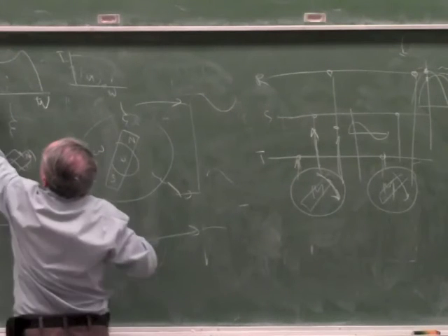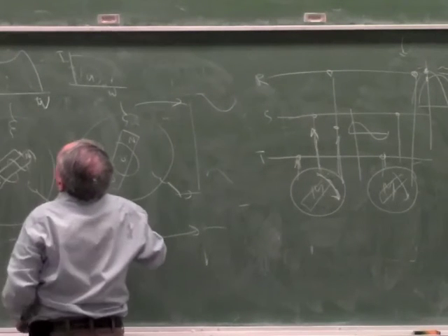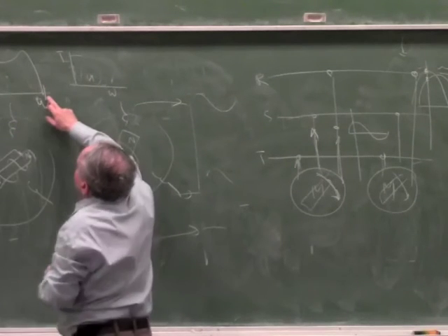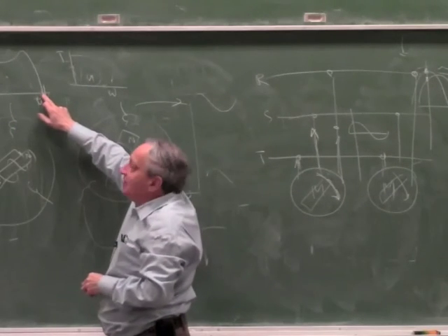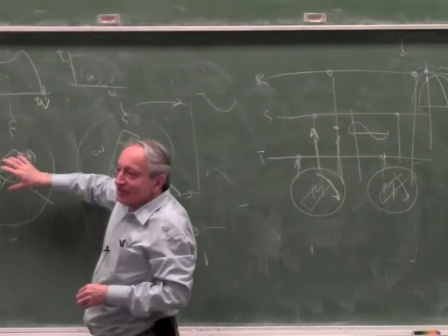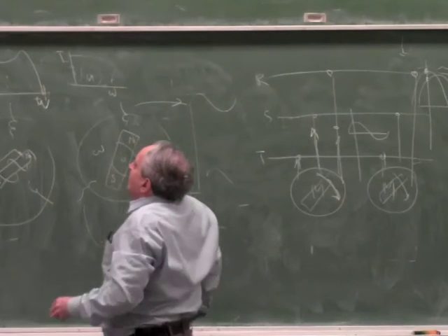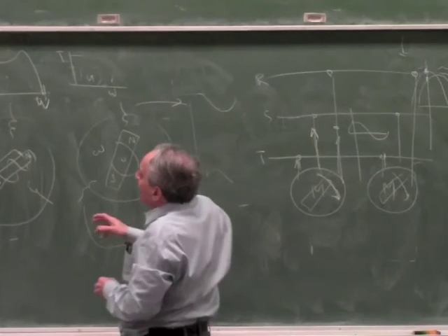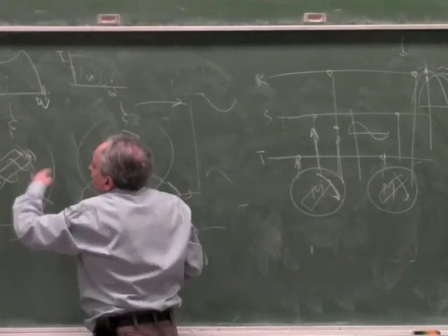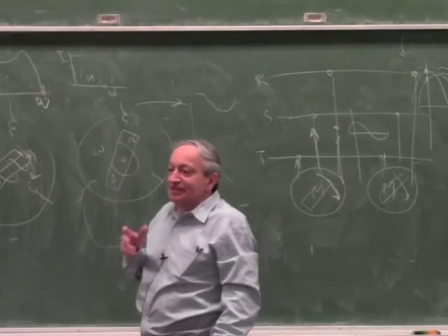So basically, if you reduce the torque to 0, it will almost hit synchronous speed. There'll still be a tiny bit of slip, because if there is no slip, it can't induce a current. Now, what happens if you take this armature and you force it to go faster? In other words, you reverse the slip.